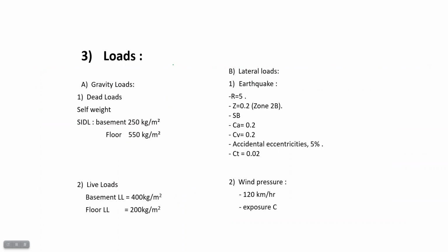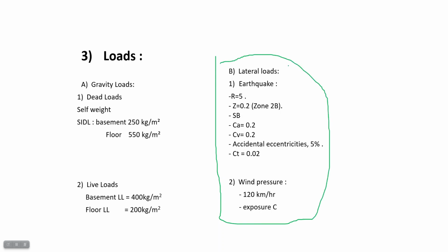For the loads, the lateral loads, wind and earthquake, are usually related to the location of the project. As you know, the location of the project is Lebanon, so we are going to check using ASCE for the specification of these two loads related to the Lebanon region. If we cannot find anything related to this location, we can just use LibNor, or the specification mentioned in LibNor.